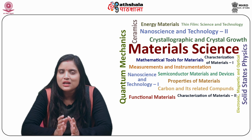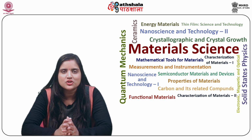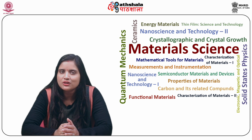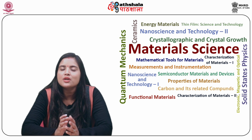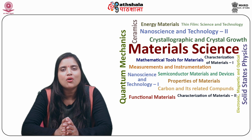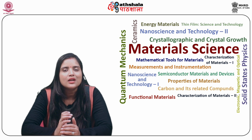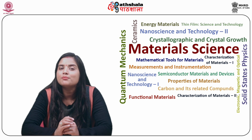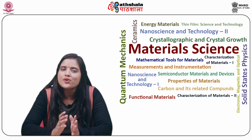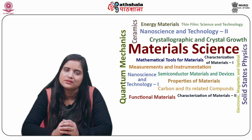While metallic electrodeposition, including reducing the metallic ions, has always been a cathodic reaction, deposition of the metal oxides is an anodic process due to oxidation of metals. Therefore, in electroless deposition of the metals, reducing agents are required, and for depositing compounds, oxidizing agents are necessary.